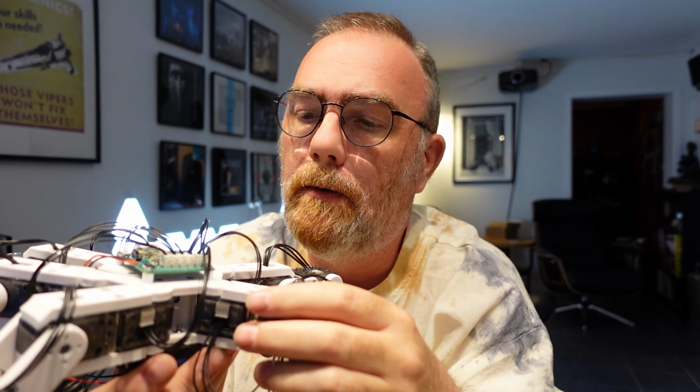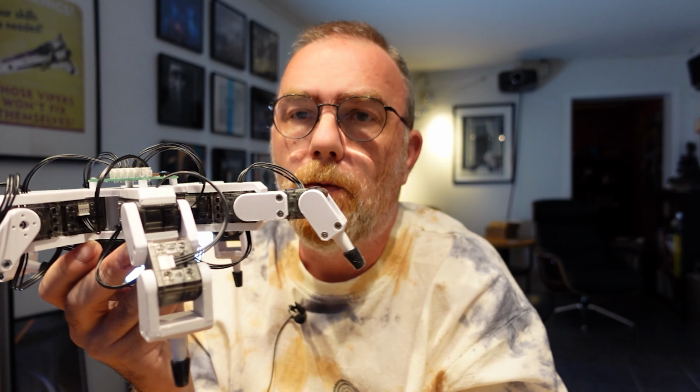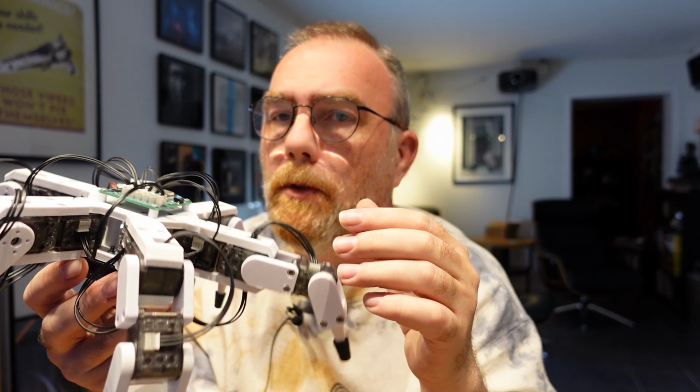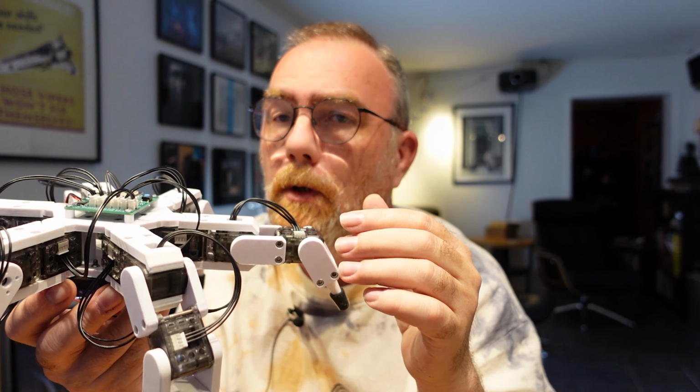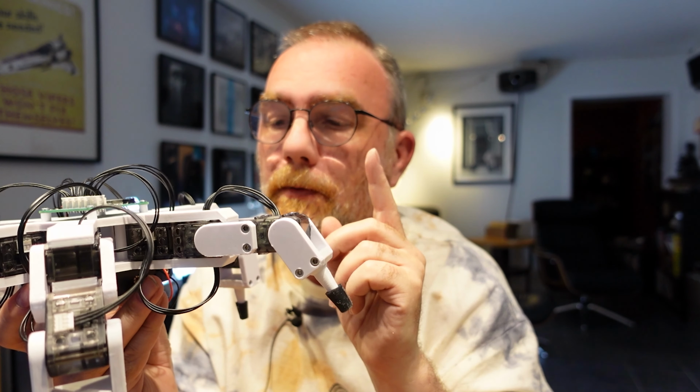I also have more transformation matrices to battle with. So when this robot is walking, I'm solving the inverse kinematics equations for the end effectors. If it's going to do stuff like pitch and yaw and roll, I need to solve the reverse of these equations.